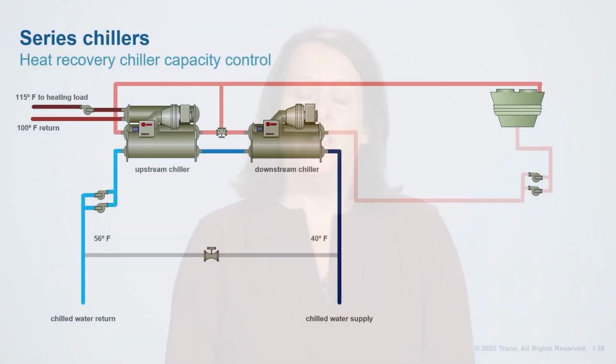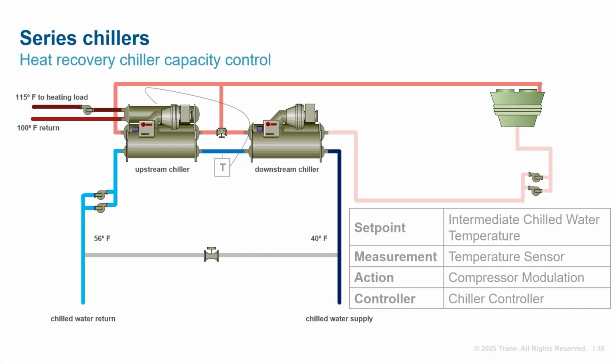In that case, the heat recovery chiller needs to meet more of the cooling load. Control of the heat recovery chiller switches to leaving chilled water temperature. Since the chiller has switched from leaving condenser control to leaving evaporator control, other means are needed to maintain the hot fluid temperature. So, at the same time, the three-way bypass valve is controlled to maintain the heat recovery condenser leaving temperature.